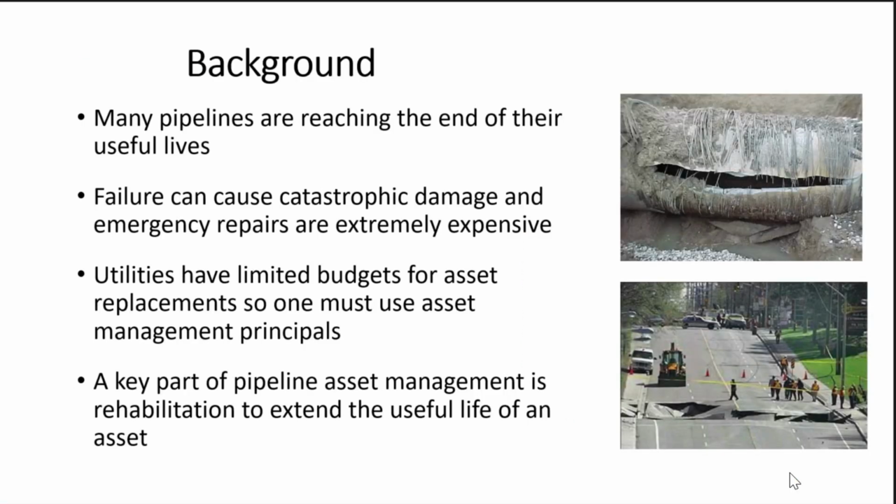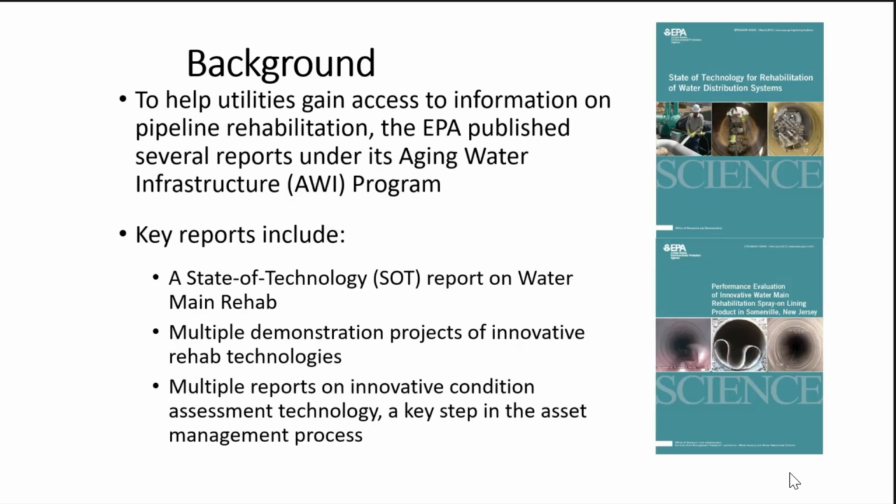When you're dealing with pressure pipe, your failure mechanisms come from within. Typically when pipes fail, they leak first, and then they can have very violent bursts. You see here a very large bar-wrapped concrete pipe where the bars had corroded and then it had an extreme, violent break. When you have these things, it can lead to very large sinkholes. It's quite dangerous. Obviously, these are extreme cases with large pipes. We also have very small pipes. When they fail, it's less consequential, but we'd still like to replace them. There are quite a few techniques available for fixing them.